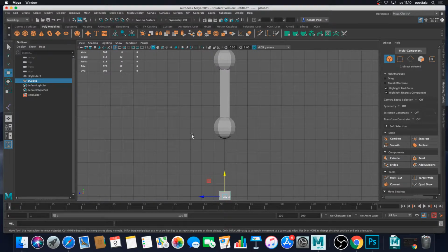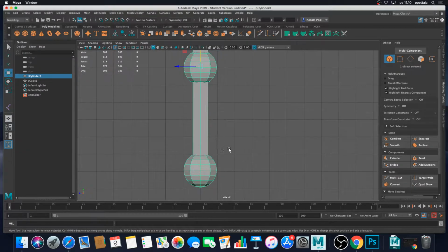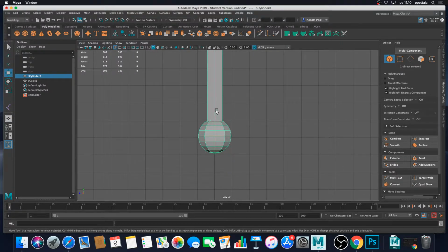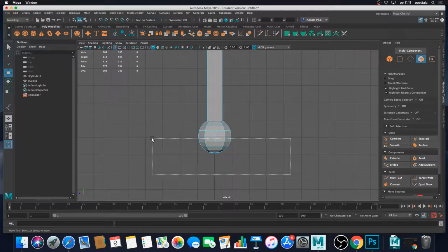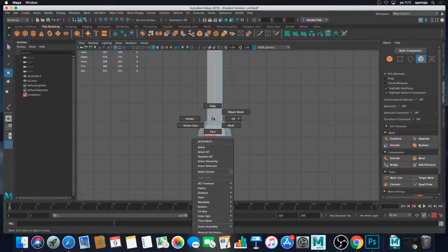Before we start to model our cube, we can actually select this arm part of our robotic arm, and then we can enter into the face mode because we want to delete half of this sphere, or these faces from our arm, because the cube is going to cover part of that, so a little bit optimization as well here. So I'm pressing my mouse right on top of my object down and selecting the face selection, and then doing the tracking selection here and deleting these bottom faces, and then pressing my mouse right down and going back to the object mode.